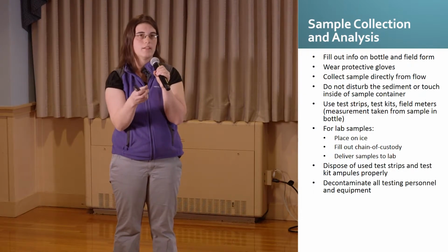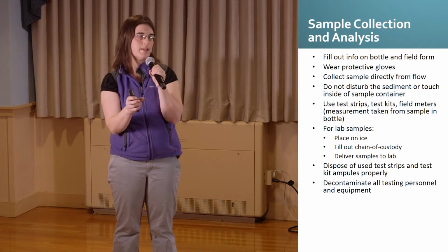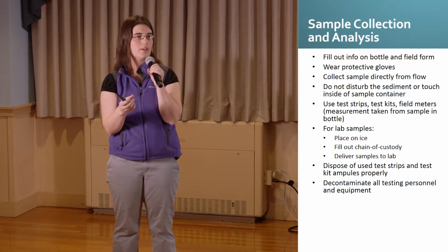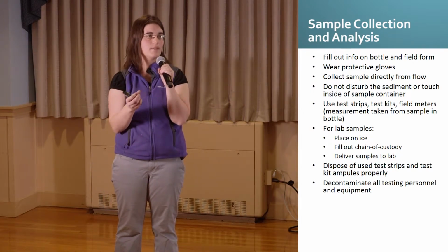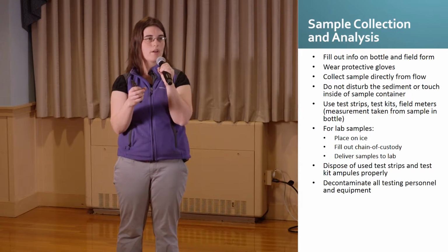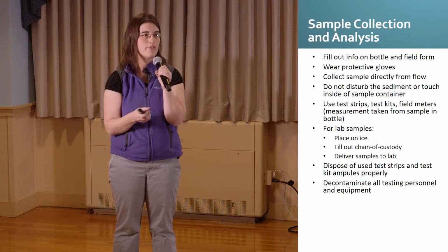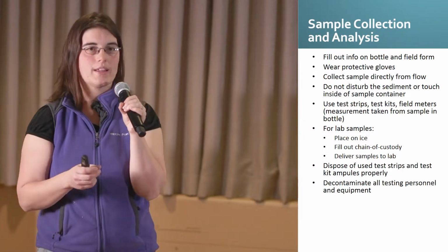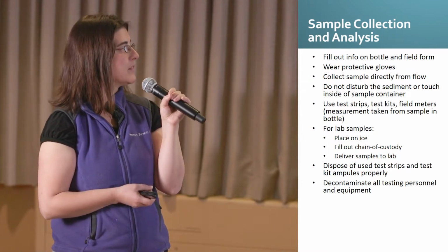And you don't want to disturb any sediment, or if you're collecting the sample in a catch basin, you want to avoid as much as possible collecting any of the sump water in your sample, because that could throw off the results. And you want to keep your sample as clean as possible.